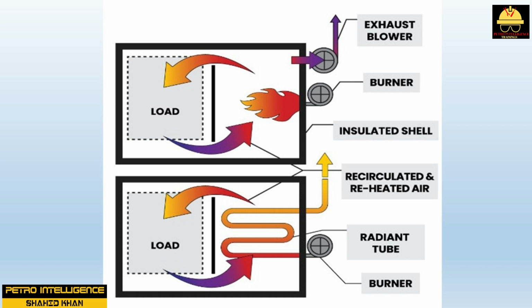Fire tube heaters are indirect-fired. They contain the combustion gases in tubes that occupy a small percentage of the overall volume of the heater. The heated tubes run through a shell that contains the heated medium. A fire tube heater resembles a multi-pass shell and tube heat exchanger.